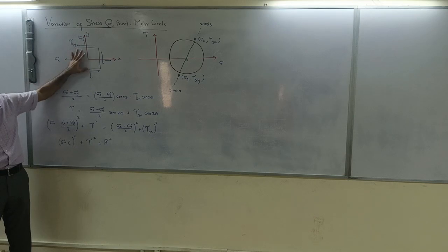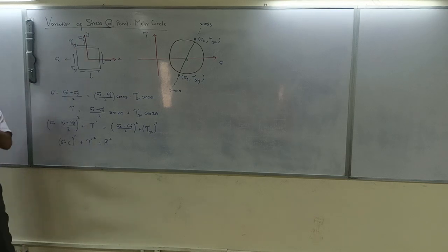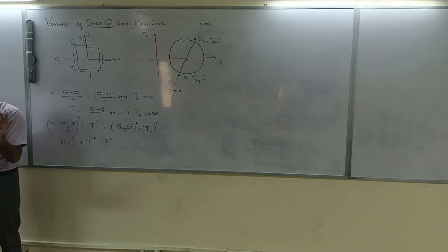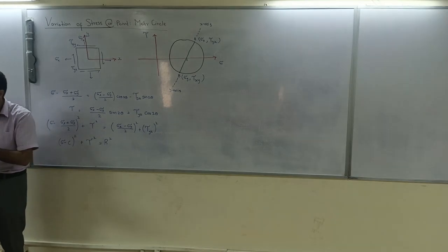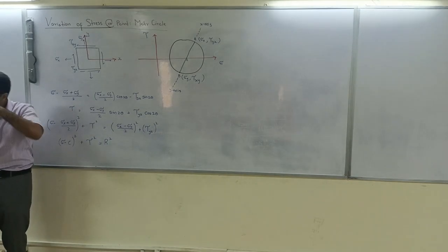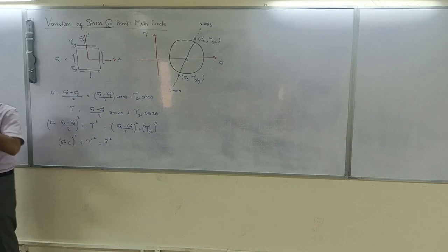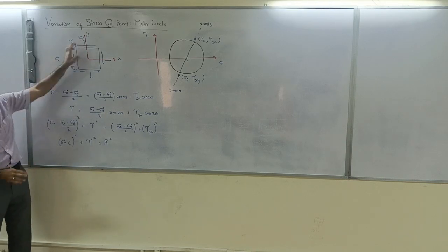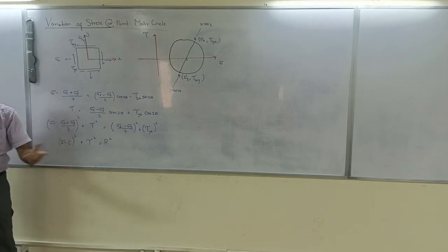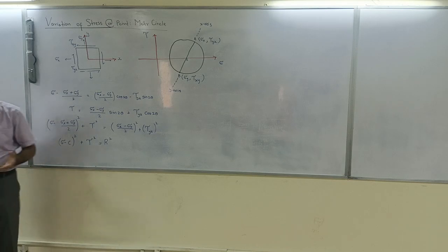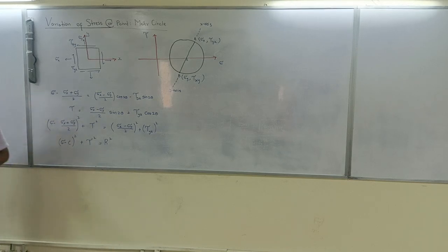Now once you have got that stress profile, those are the points which you have determined in the lab and where you have placed your strain gauges. Those are not necessarily the points which are giving you the maximum stresses. The maximum stresses will be at some inclination, and you have to rotate to find out the maximum stress. That's why we are having these arguments since the last 2-3 lectures, on how to find that maximum.